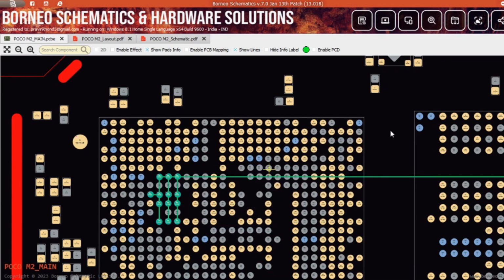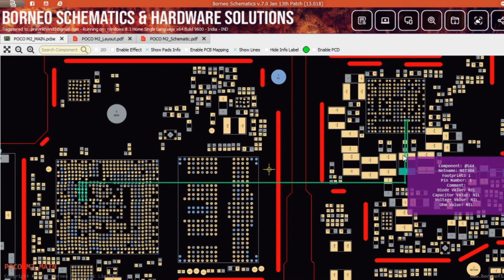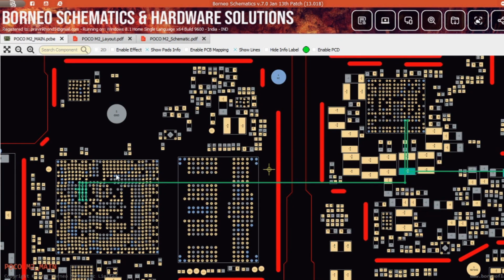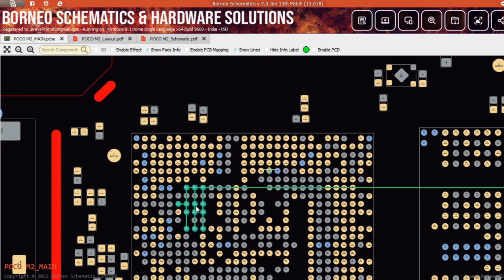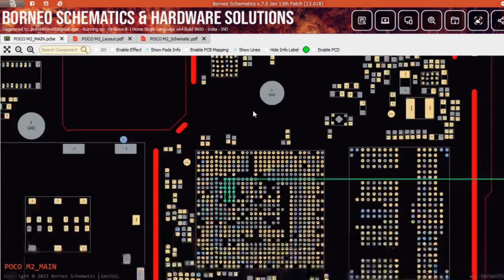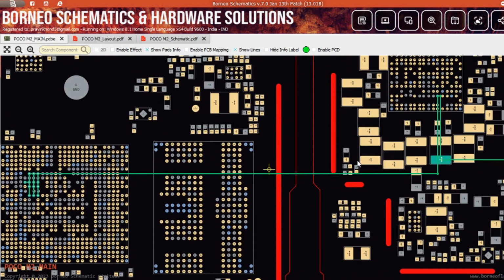Now first condition. I'm telling you, if you check here in this capacitor, you will see the reading is okay. Also, I mean to say the diode value is in a good condition. Also the voltage is here. But somehow if any ball is not connected to the CPU, the CPU does not boot and your phone does not work, in a dead condition. I hope what I'm saying to you is clear to you.